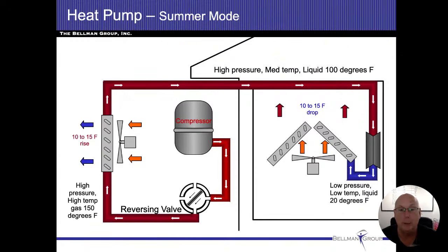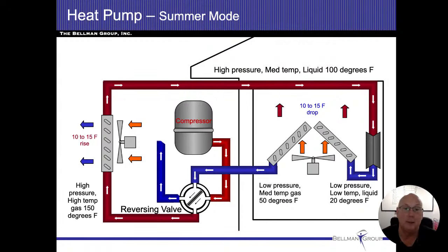That liquid comes to our indoor coil, where we're going to be absorbing heat. At that point in time, it changes state, and in the change of state, it's going to leave as a gas, where it's going to go to the compressor and get pressurized again. And when it pressurizes, it increases that temperature again.